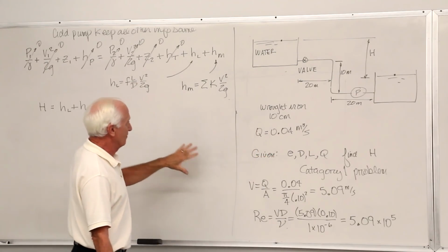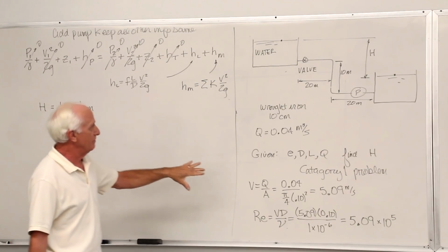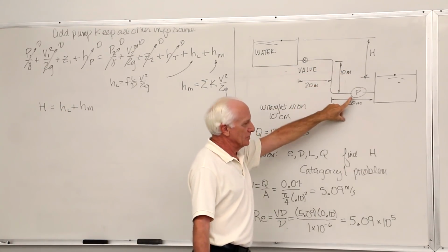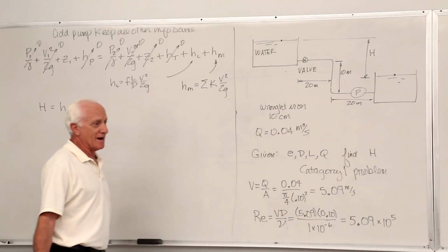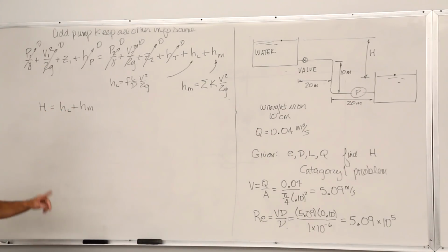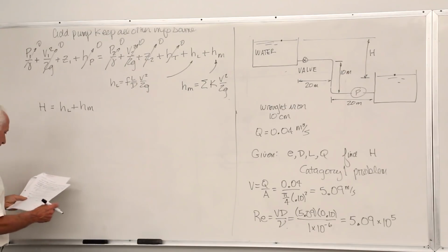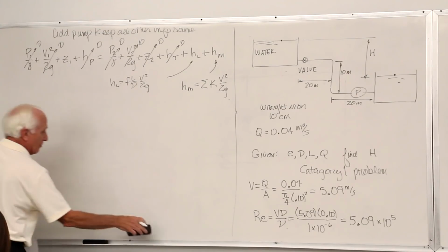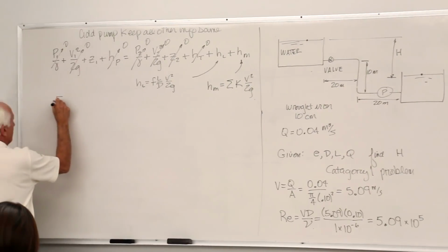Everything is the same. I take the answer from the first part, which was 22.4 meters. I put that in here for H, and now I want to see how much power has to be provided by that pump to the water to do the job. So find the power needed by the pump.